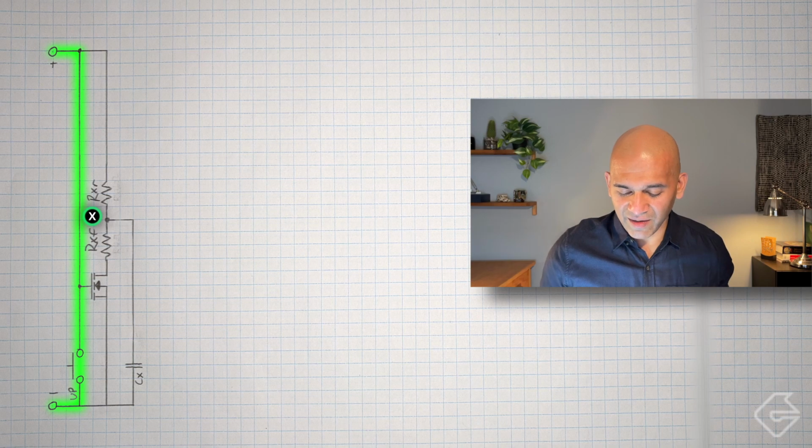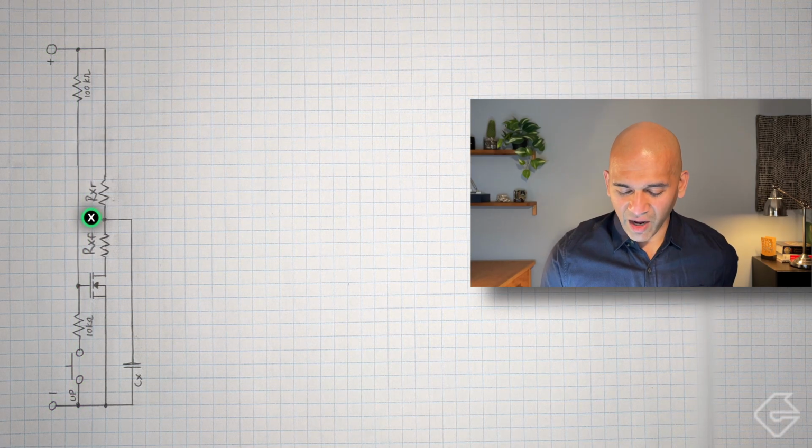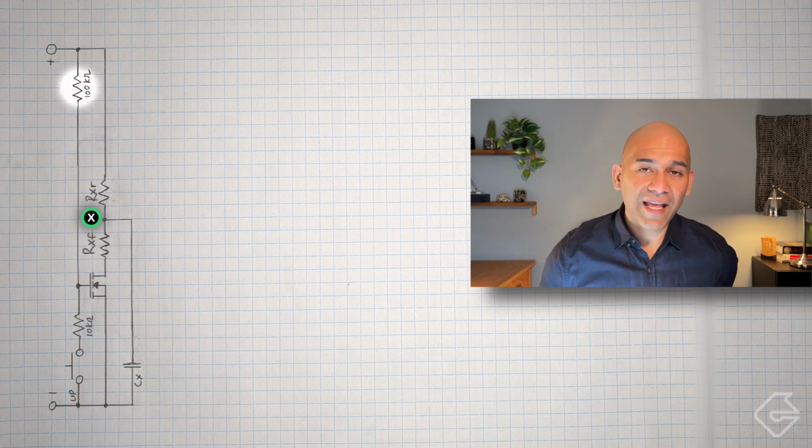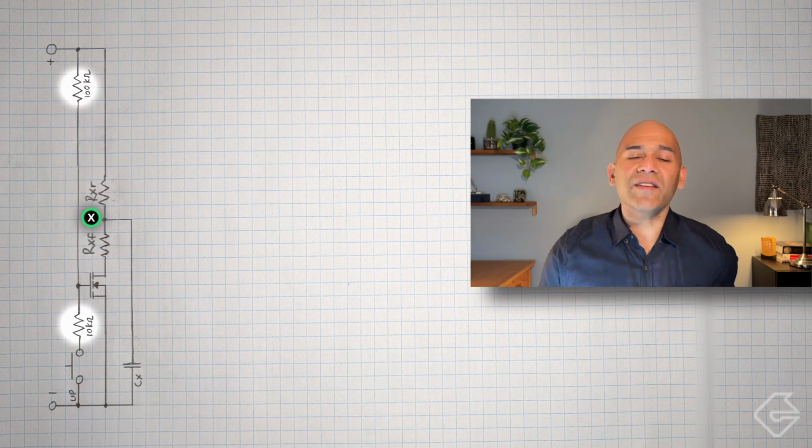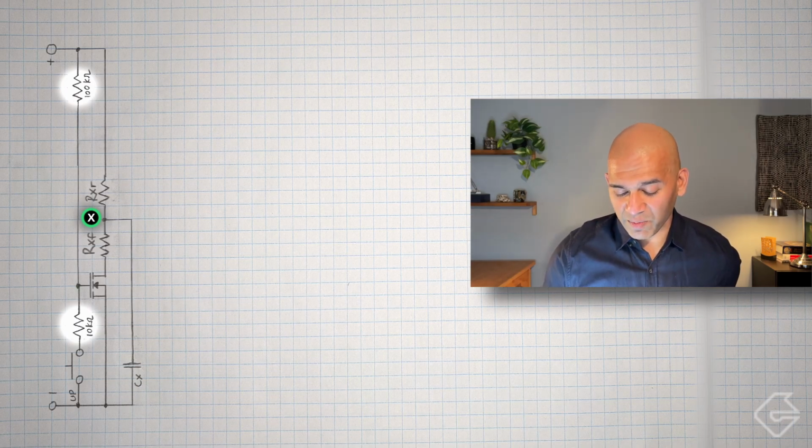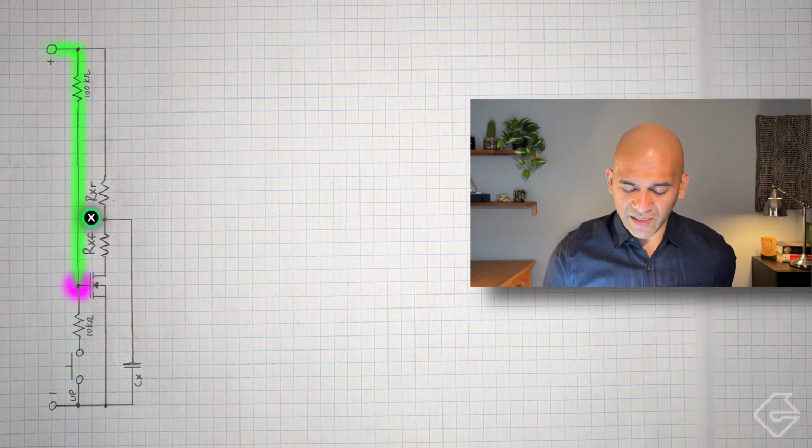In fact, without anything in here, that's a short circuit, so not good at all. So I put a 100 kilo ohm resistor over here and a 10 kilo ohm resistor over here. That's going to make sure that the current going through that switch is extremely small, but it's also going to make sure that when this is pressed, this node over here goes close to 0, and when it's released, it's going to be a nice solid 1.